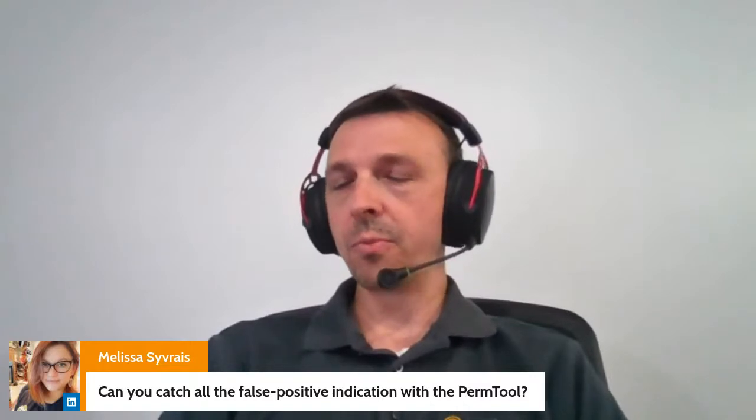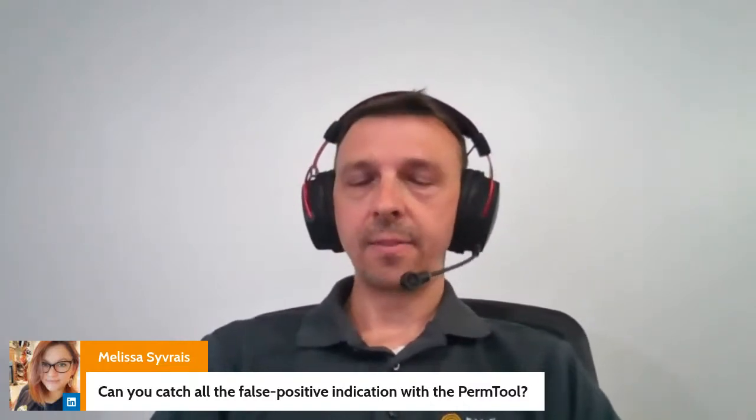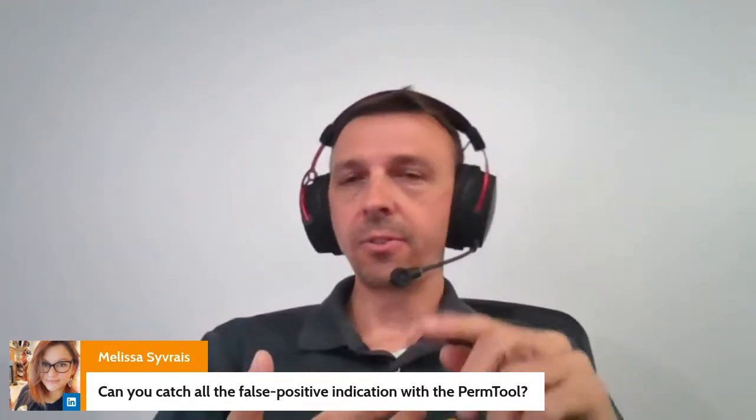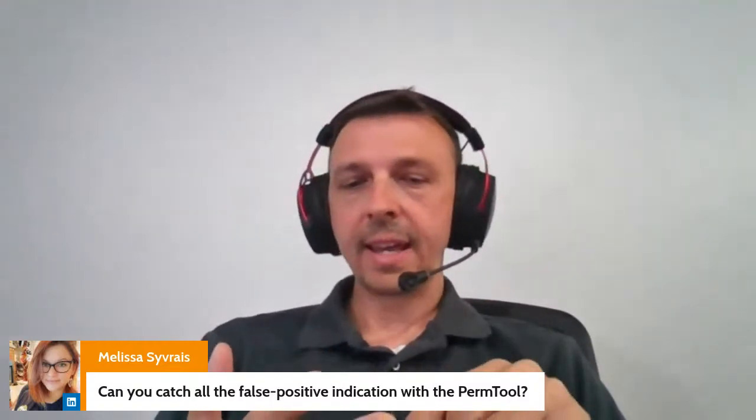The question is, can you catch all the false positive indications with the PERM tool? No. The PERM tool is there to help you assess if the indication has a typical signature of a true wall loss or a false positive. The response of the PERM tool will be true most of the time. But again, if you remember, we need three things to make a call: the C-scan, the signals, and the context. Taking into account the context is always important to make a call.